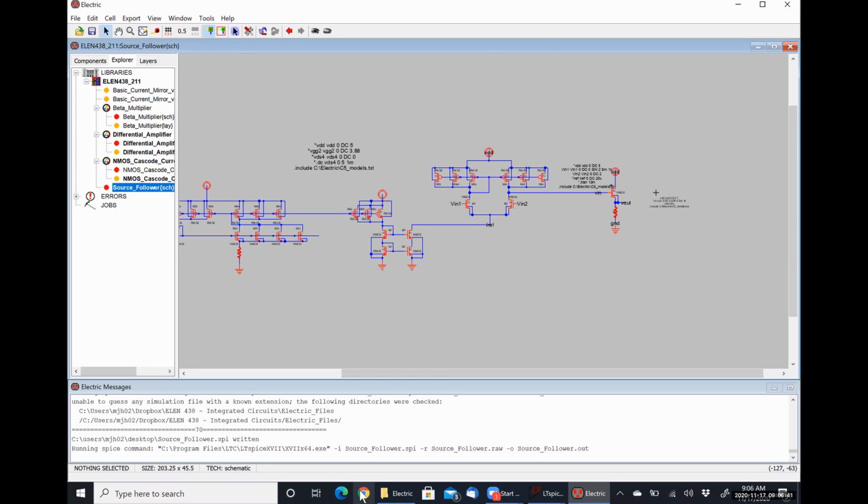Dr. Harlan, I have a question about a circuit I'm building. I have an Arduino running some servos, and it works fine, but if I load the servos too much, it shuts the Arduino off. And I think it's just pulling too much current to the servos. You're probably pulling too much current, and it's overheating the voltage regulator on your Arduino, which will cause the whole thing to shut down. I've noticed students doing that a lot.